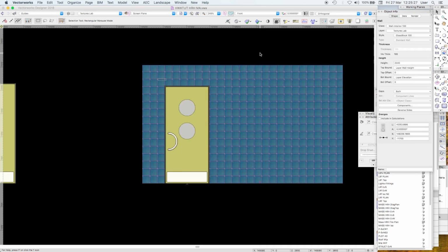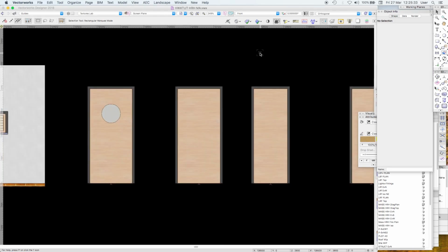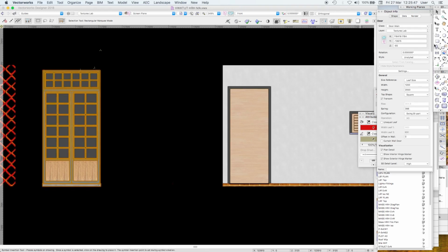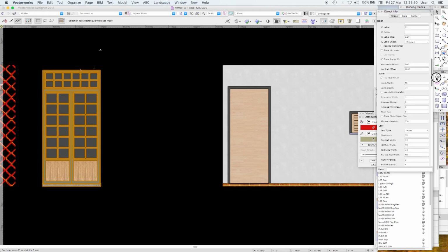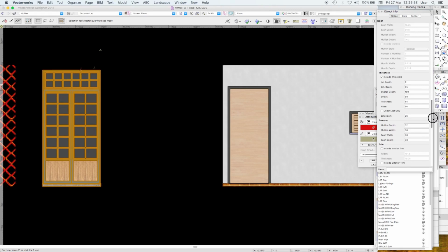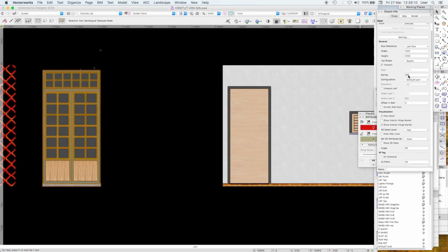What I want to come along to actually is, we'll just scroll through this little kitchen hatch. You can have a lot of fun. This has a transom. It's a panel door with two panels, and the bottom panel has a set height. By the way, if you remove the transom height, the door size changes. You'll figure that out. So the control of the transom, there's the spring height. Spring height sets the transom height.